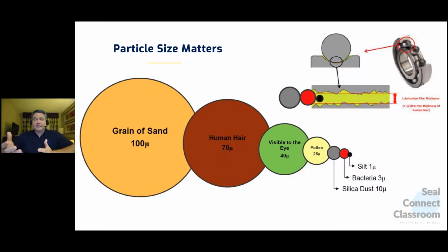So when you hold up a sample of oil and it looks clear and there's not any particles, the particles that you can't see, that's what is really damaging your equipment. Those larger particles typically don't fit into the bearing clearances. They settle out. They have more density, more weight. They settle into the sump and they're swept out of the way.